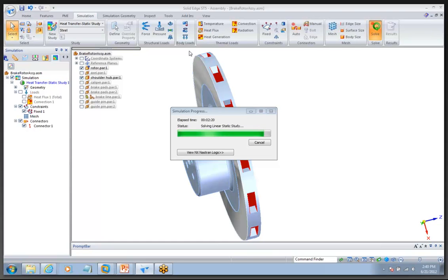We can say with Newton's law of cooling that the temperature of this surface minus what they call T infinity, which is the temperature of the air way away from that surface, times a certain constant is equal to the heat flux. That constant is called the convection coefficient. The convection coefficient is not as easy to just look up. It's dependent on the material, on whatever fluid you have, and also on the geometry. So you're going to have to spend a little more time researching what convection coefficient you want to use.